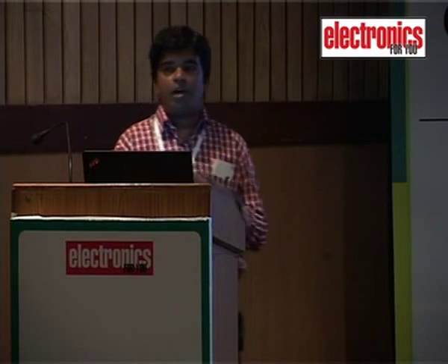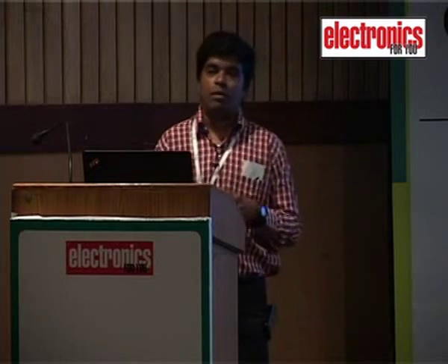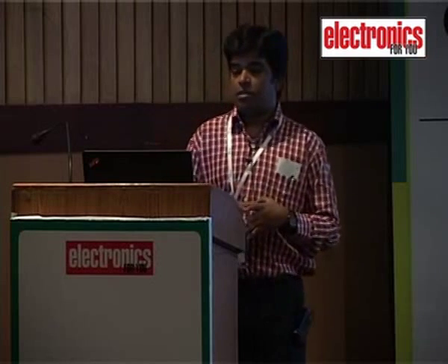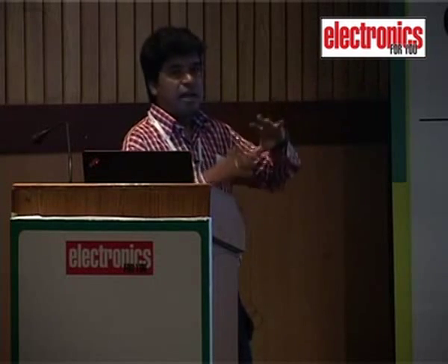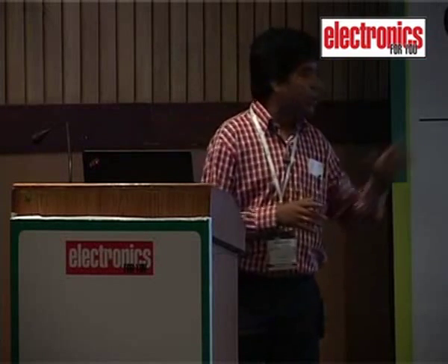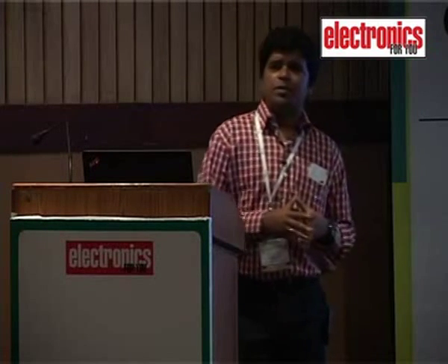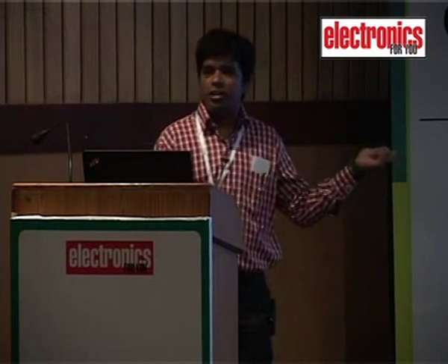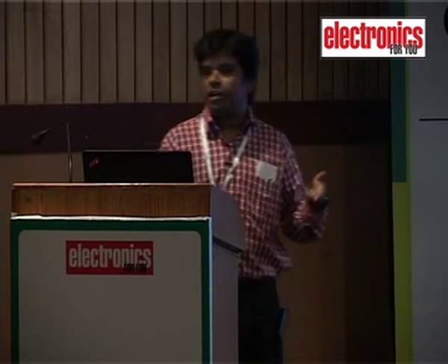Going ahead, when we have our ROM modeled, the model of ROM available in VHDL in 2 dimensions, how do we want to use it in simulation? Typically in simulation, if we look at a blue background as the entire test bench, we have one DUT model, a design under test. We have implemented some kind of compression or image processing algorithm, even filtering, and for that we need to feed an actual image. So we could simply instantiate a VHDL model of the ROM that we created from our approach, and subject it to the simulation.